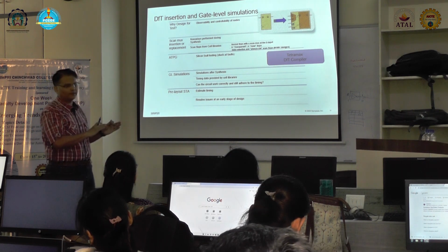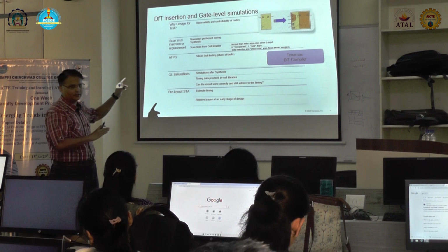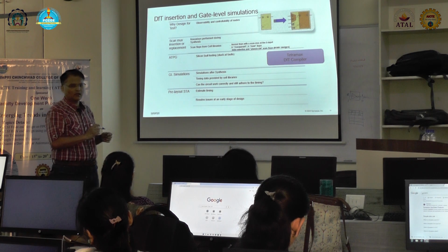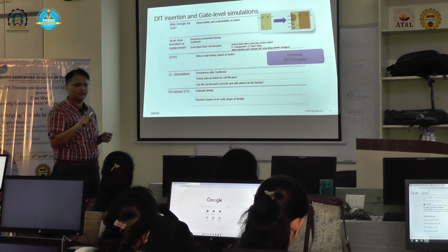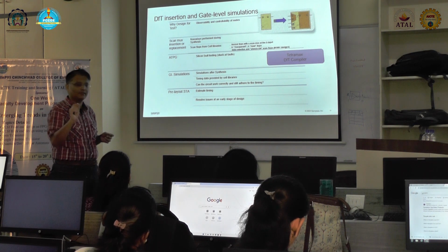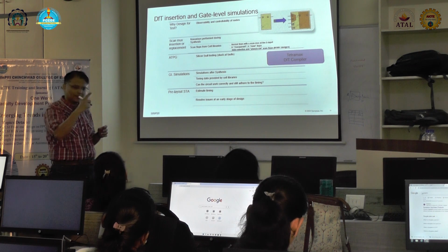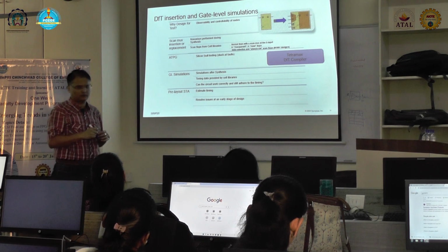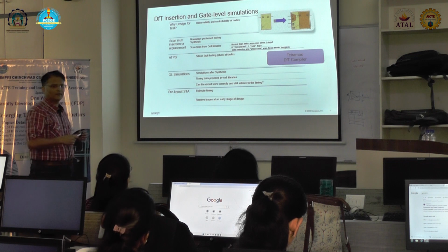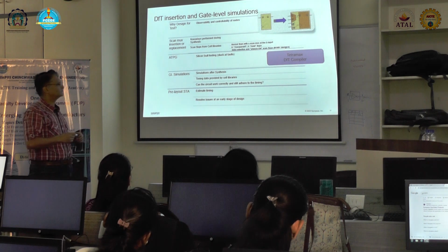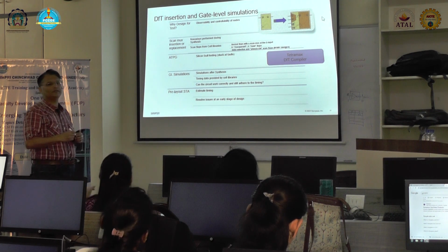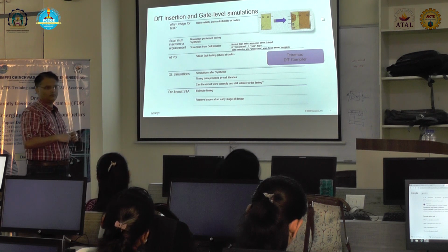So boundary scan is different, and the scan that we are talking about is different. The DFT deals with each and every point, whereas boundary scan only operates at the inputs and outputs, only the connections. So it is more to do with board level testing.